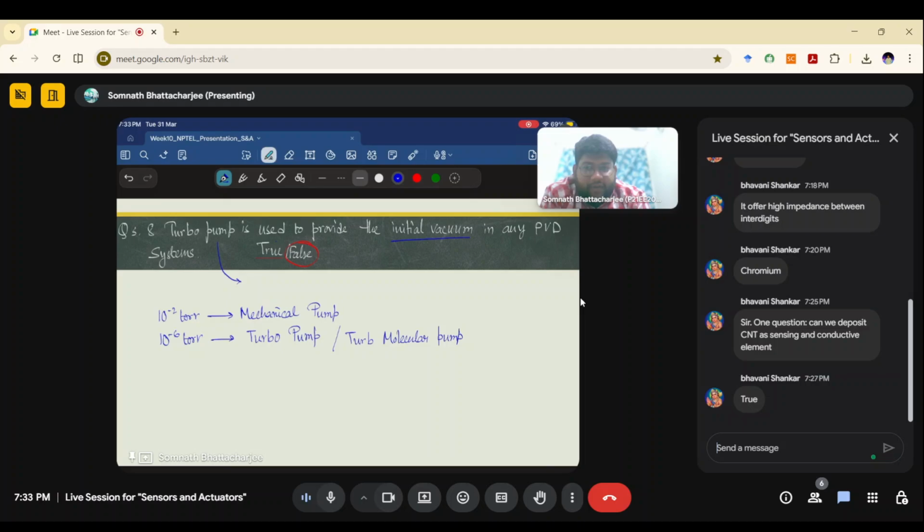So that was kind of a hoax, because a turbo pump within a second reaches 10 to the minus 4, and because of that sudden change in the vacuum, it will distort the materials and your samples and everything. So you need to have a gradual change.